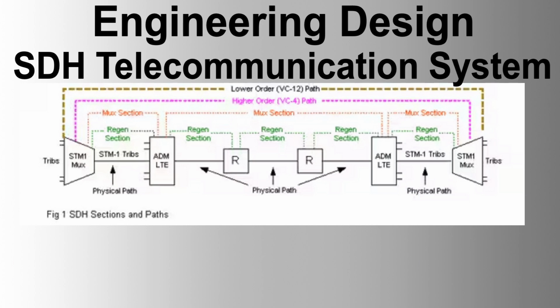System availability. Overall availability. The telecommunication system shall be designed to meet an overall availability criterion of 99.99%. Critical components. All active devices that can form single points of failure along the communication network shall be avoided, where reasonably possible, for critical subsystem components.